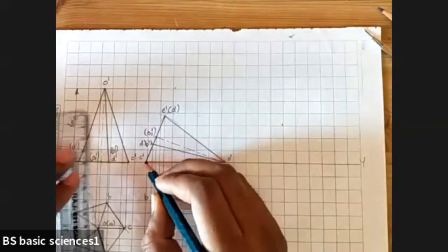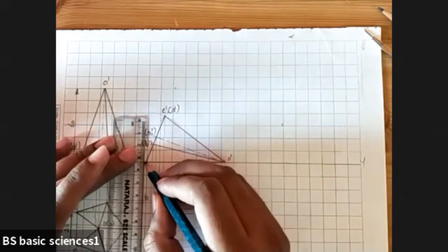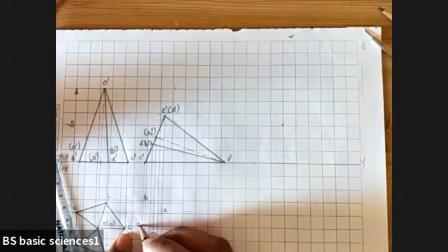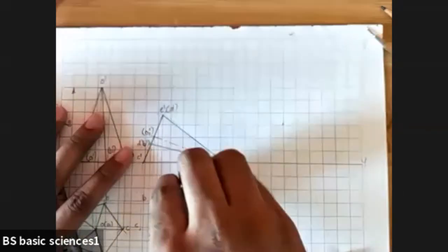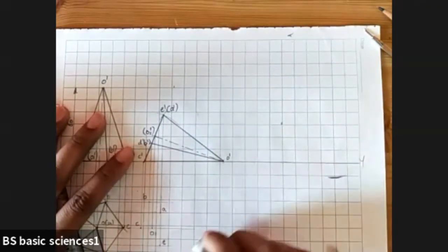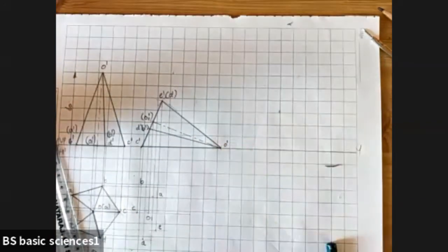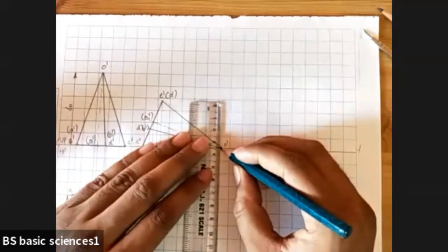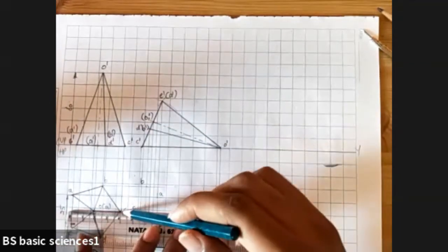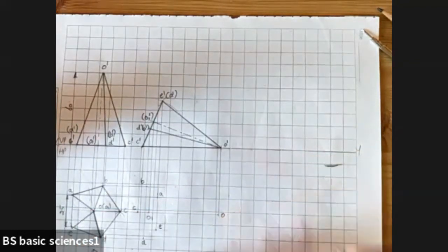And finally, the last point which we have is C. Drop it down until it coincides with the point C. So this will be point C. Erase the external lines, whichever you get here. We are left with one more point, that is O. We are supposed to drop that also. Extend it until it meets the axis. This will be your point O.